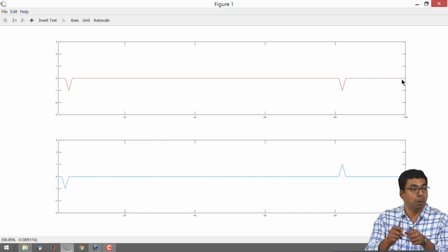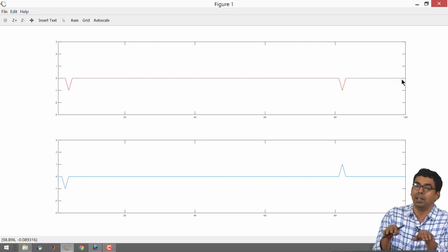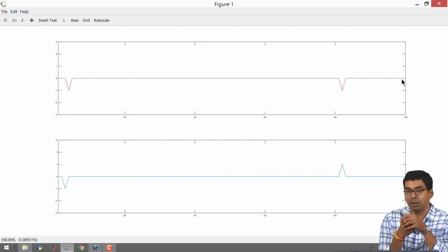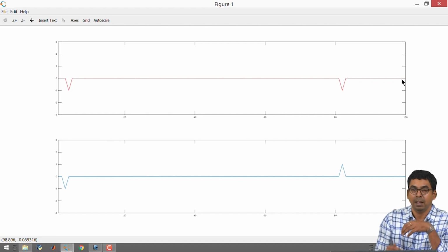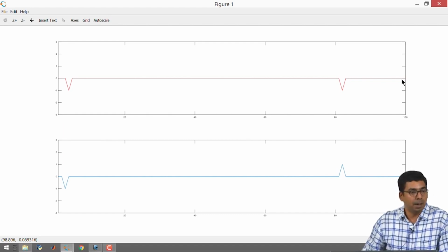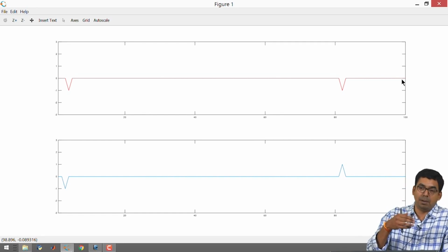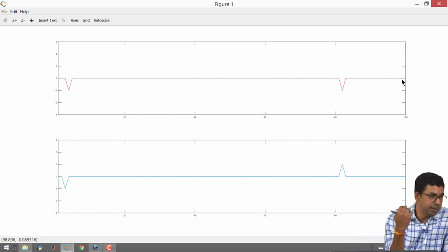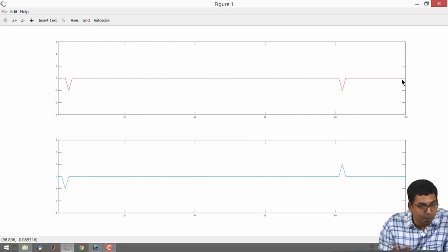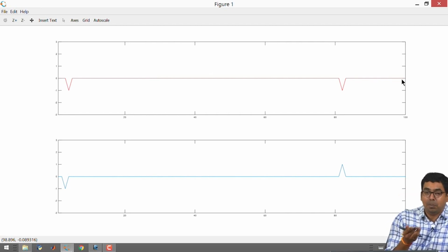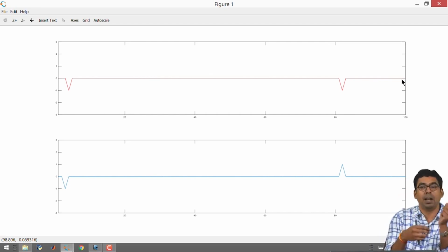Maybe the transmission line is broken, or the insulation is breaking down and something is shorting the forward and the backward conductor. If we know the location and the kind of fault we are looking for, it makes it easy for us to go to that particular place and fix something. So what people can do is take a transmission line, launch some voltage from one side, and wait for the echo from the other side. If it is not flipped, then they know it corresponds to gamma equal to 1, or the load resistance being open circuit. So there is a breakage of the transmission line somewhere.